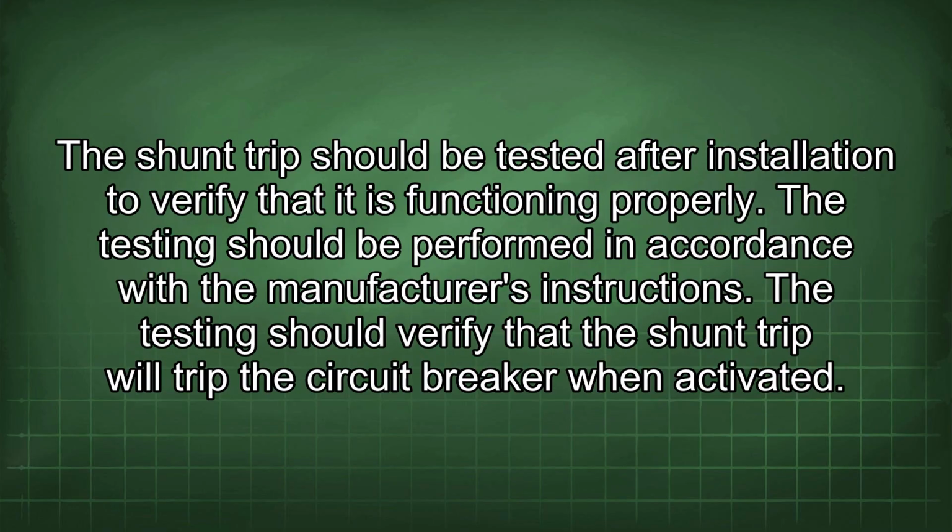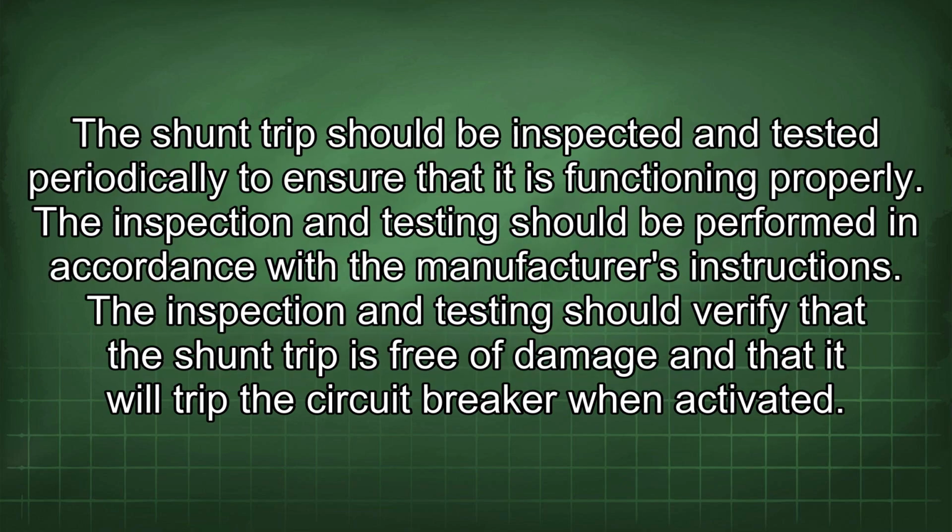The shunt trip should be tested after installation to verify that it is functioning properly. The testing should be performed in accordance with the manufacturer's instructions. The testing should verify that the shunt trip will trip the circuit breaker when activated. The shunt trip should be inspected and tested periodically to ensure that it is functioning properly. The inspection and testing should be performed in accordance with the manufacturer's instructions.